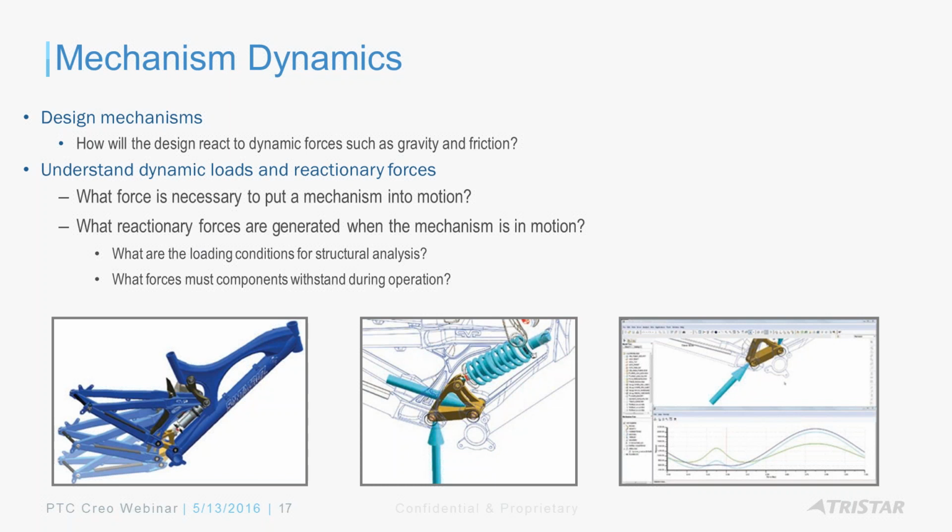It's a rigid body motion, right? Wherein you want to apply density, right? You want to enable gravity, apply some external loads, and some dynamic entities within mechanism, and get forces, and then export those maximum forces out to Creo Simulate and run a full-fledged static analysis on those for those worst case or maximum force conditions.